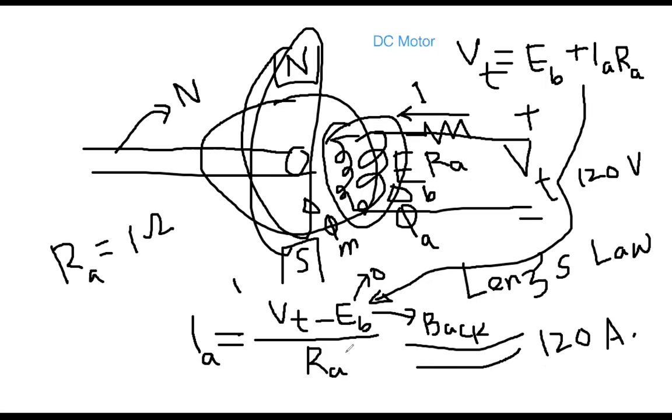Now everybody see the equation. At the beginning of the operation, if you add some parameter, this is called the starter resistance, RST. This is the word, starter resistance. Okay, so therefore, you have to add a very high value of starter resistance. If you add that starter resistance, then your current value will be small and that will protect the motor.